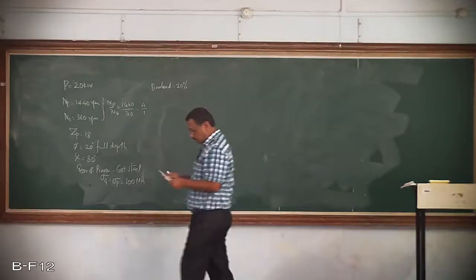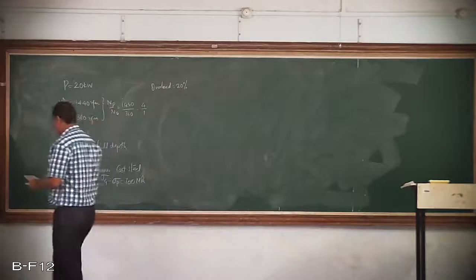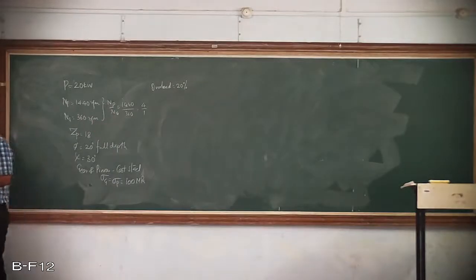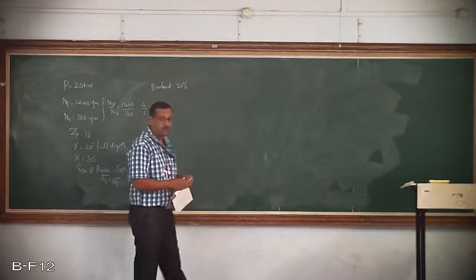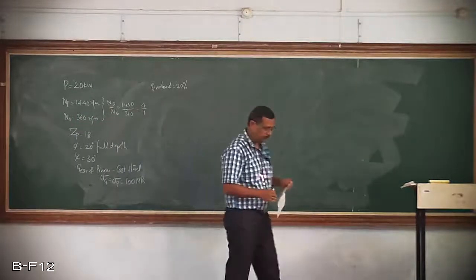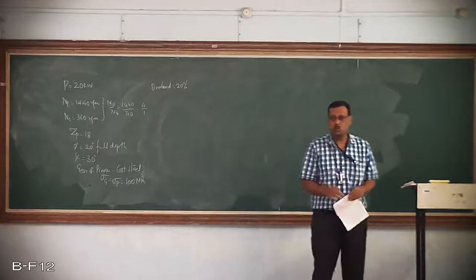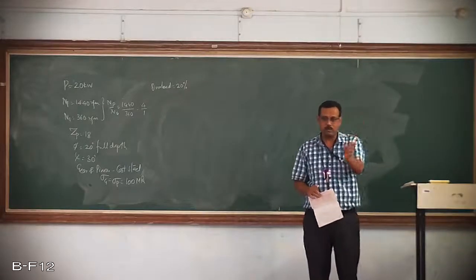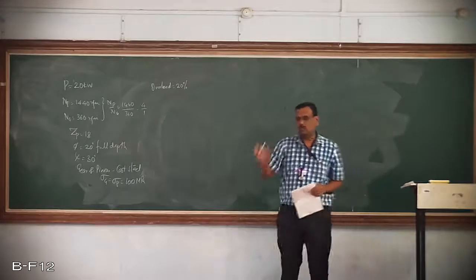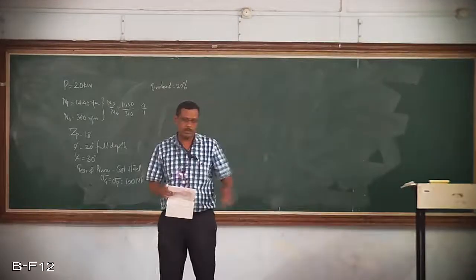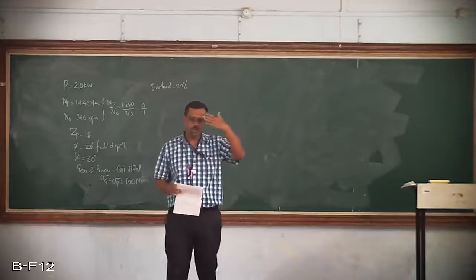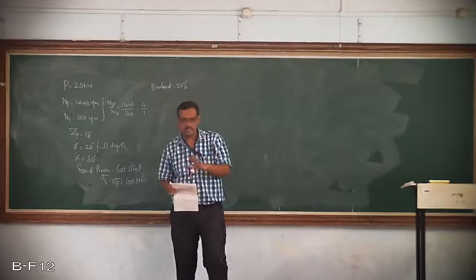Now, to proceed with the design, the steps involved are: first, check which is the weaker member. That is using sigma into y. Calculate sigma into y for the gear and sigma into y for the pinion, where sigma is the strength and y is the Lewis form factor. You can make use of those equations related to 14.5 degrees or 20 degrees full depth or stub tooth.